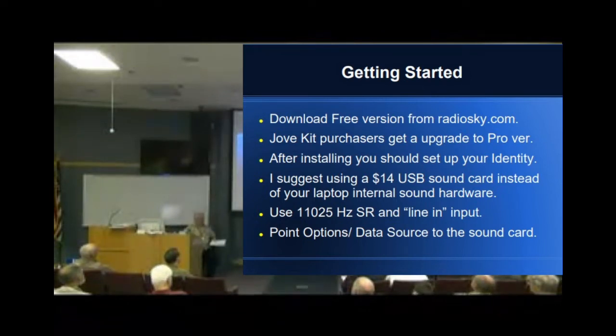Some of them have terrible offsets, and some of them you can only use a microphone input, which has lots of its own problems. Like it can have AGC on it. And so even though you go to all this trouble to get your receiver to disable the AGC in the receiver, when you send it to your computer, it applies AGC because it thinks you're not talking to a microphone loud enough.